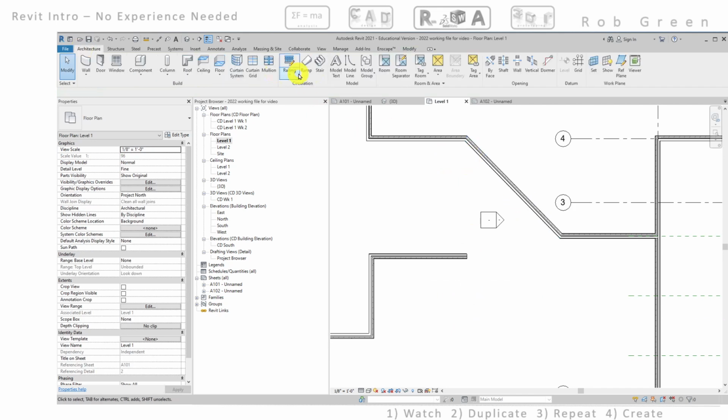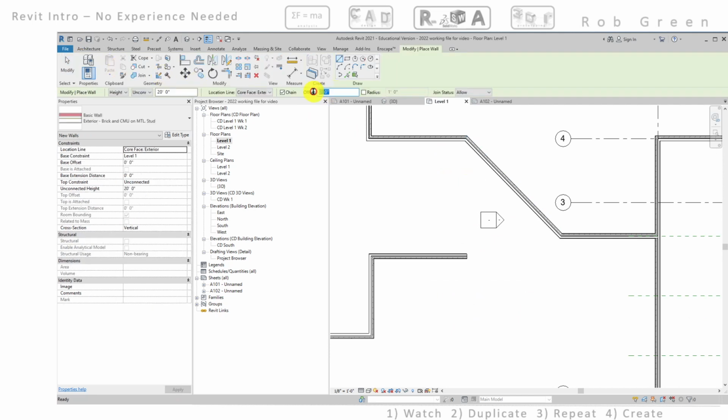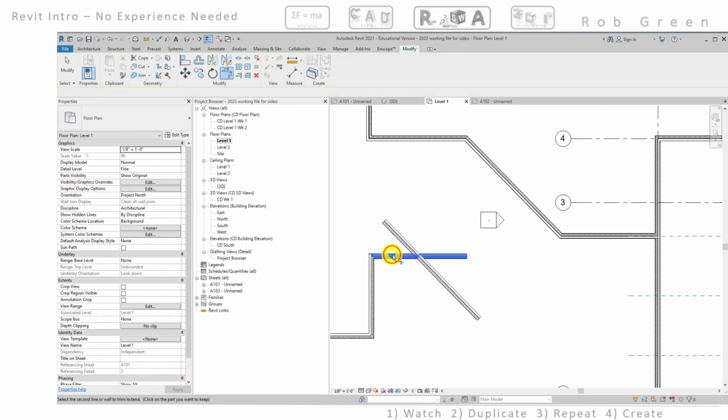And then I need to offset this wall. So wall command, and my offset is supposed to be, looks like 30 feet also. And approach my wall over here. I need to make sure which way I'm going. Yeah, pick line option. That gets me a direction of which way I'm going. Click that and trim to a corner.